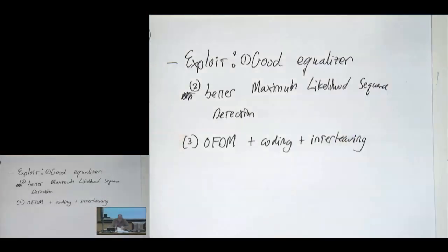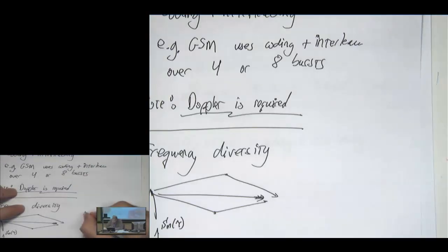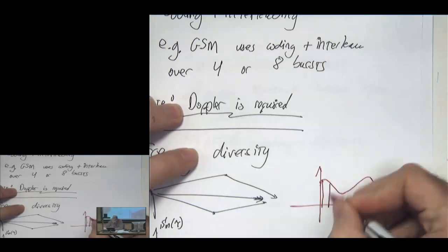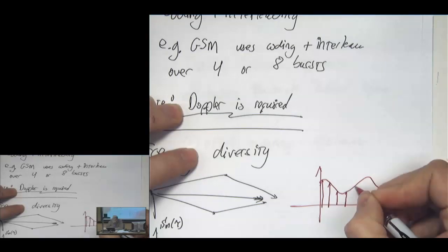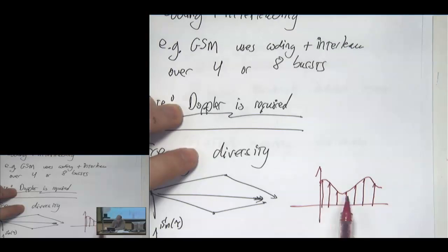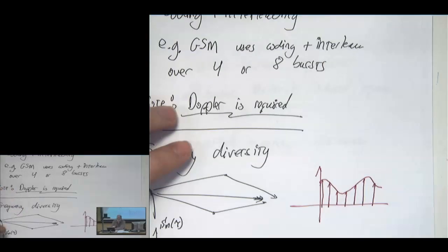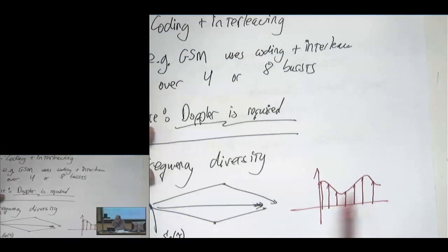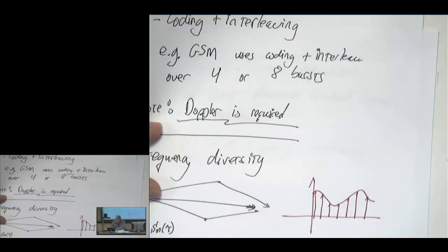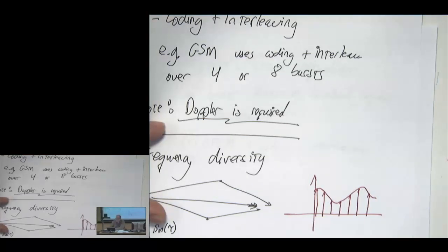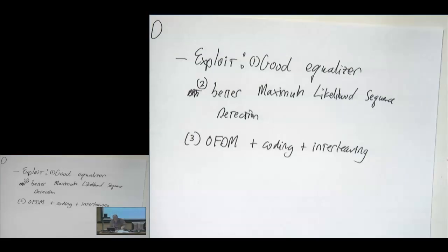Why this works is that, remember, this frequency diversity effect is going to create a channel that's frequency selective, and we're sending information on these different discrete time subcarriers. And some of them will be fading and others won't. And just like with time diversity, if you have coding and interleaving, you can get some resilience to these deep fades. It's also why all OFDM systems have coding and interleaving built in, because you have to get resilience to this fading. And if you have two taps here, this is a channel with 1, 0, and so there's going to be one point where the channel's fading. So this is actually quite a deep fade. The more taps we have, the more variation we'll get and actually better performance. So that's how you can exploit frequency diversity here.